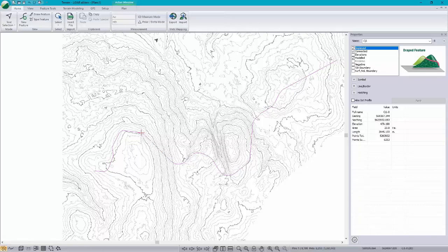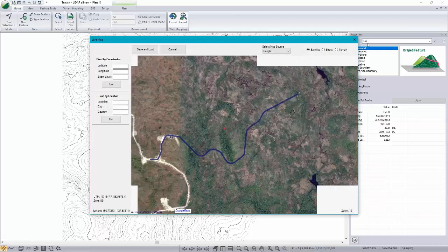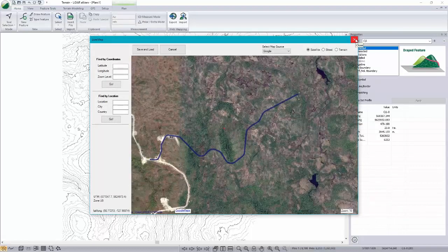For this example, we were able to bring in all the data, and now I'm going to do the thinning after the fact. I'm going to use our, whoops, I clicked on the wrong button. I'm going to use the terrain modeling simplify. Oh, well, I might as well mention this while I'm here. This button I clicked on by mistake is the new Live Maps import that allows you to bring images in from various sources.